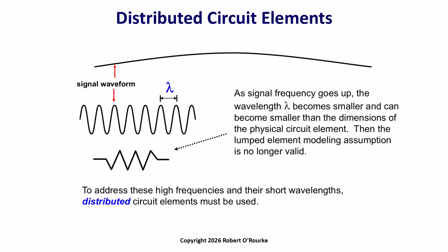Lumped element modeling, including SPICE simulation, is valid for frequencies as long as the wavelength is large in comparison to circuit size. There is no one single frequency limit value for all situations, and one must do consistency checks to make sure that the validity works in your application.